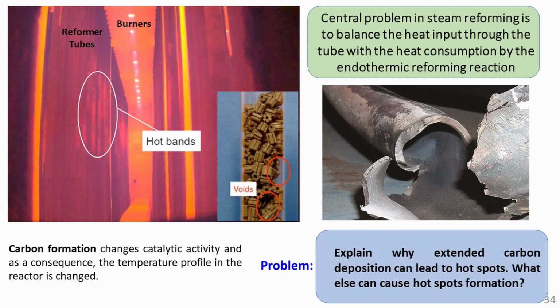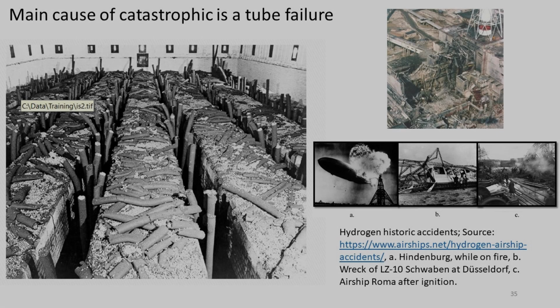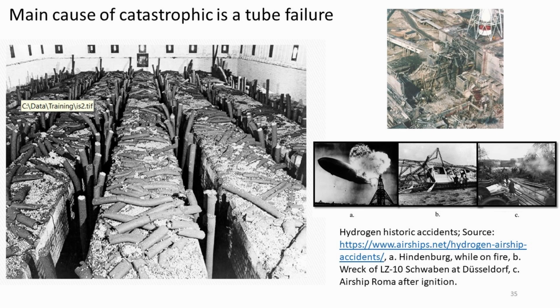This means that for a given tube, its life is very sensitive to small changes in the maximum tube wall temperature. However, high catalytic activity is essential to ensure low tube wall temperature. A high catalytic activity can be utilized to absorb the same reaction heat at a lower temperature.